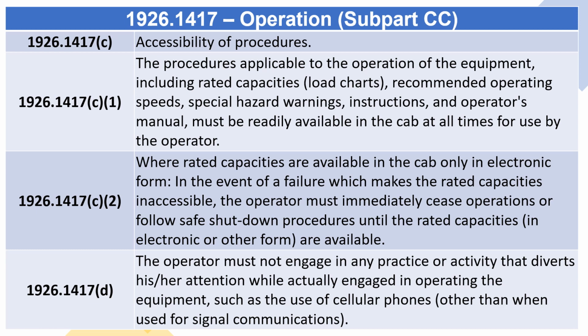1926.1417(d): The operator must not engage in any practice or activity that diverts his/her attention while actually engaged in operating the equipment, such as the use of cellular phones, other than when used for signal communications.